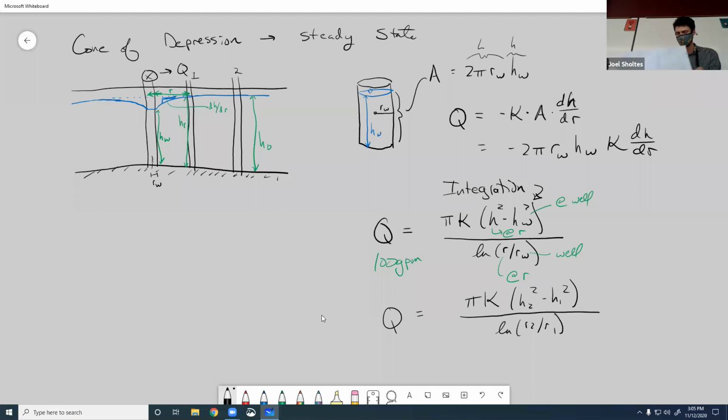They usually do this relative to the well or elevation. What you measure is the depth from the well casing top, right? So you put a little tape down there and then it hits the water and it beeps, and then you read off the depth to the water. So you can set H as some arbitrary datum. You could say, okay, my aquifer is going to be 100 meters deep, and then you just subtract what you measured from that. So it's all in terms of H. You could rewrite that in terms of depth to the well, but we put it as H.